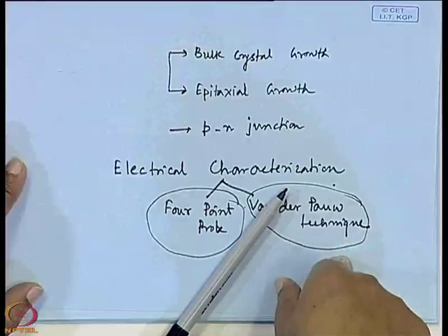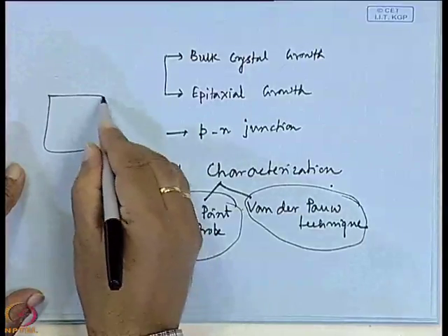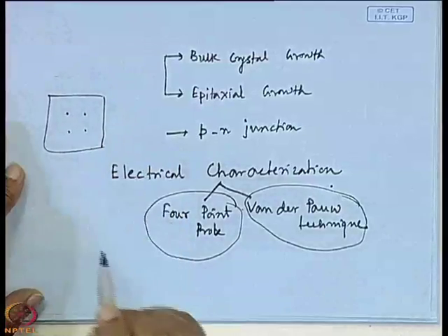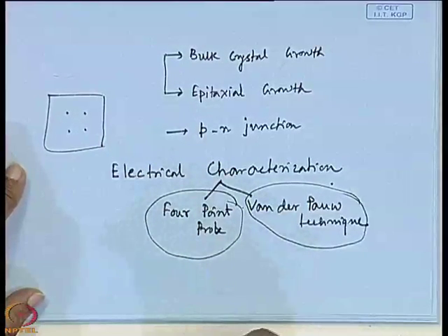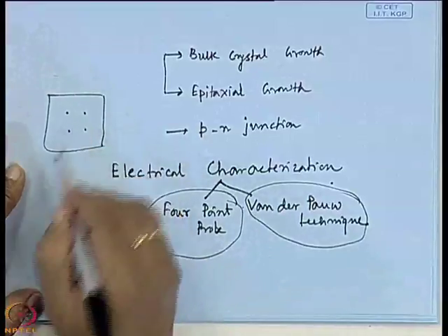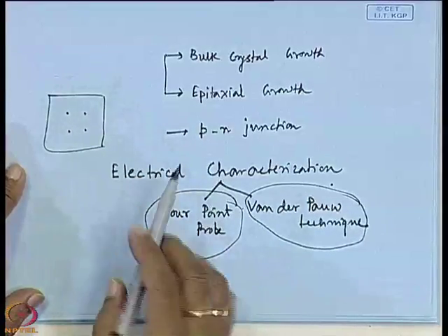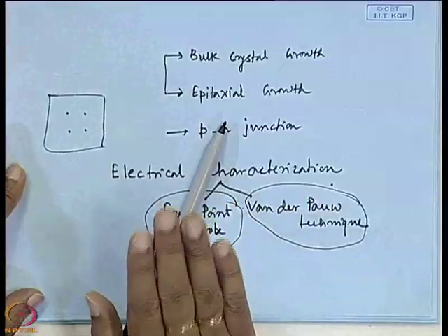But for the Van der Pauw technique you must have ohmic contacts on your samples. When we talk about ohmic contact, it means first you take the sample, clean it, then make 4 metal dots on it, of say 1 millimeter diameter, and these metal dots are thermally evaporated on the surface of the material to be characterized.